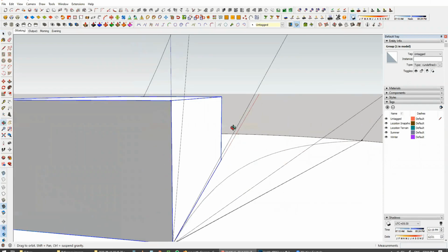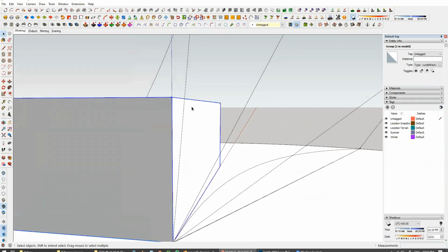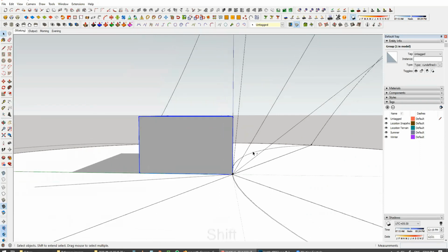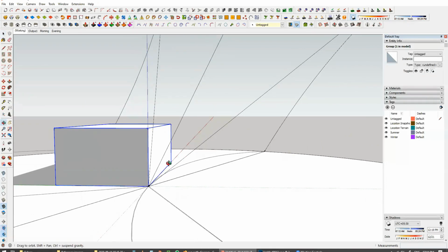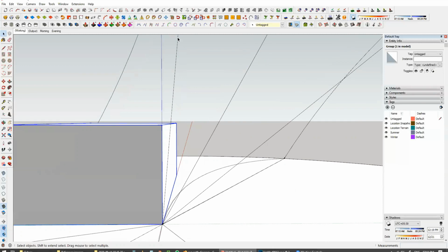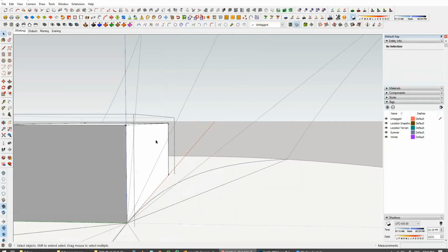So now for this location, this face will receive the sun throughout the year, because we know that it is receiving the summer sun, because you can see the angle is at an inclination. It is receiving the equinox sun, and it is also receiving the sun from the winter solstice. Now we want to block it for the summer solstice. Now for that we can have a projection.